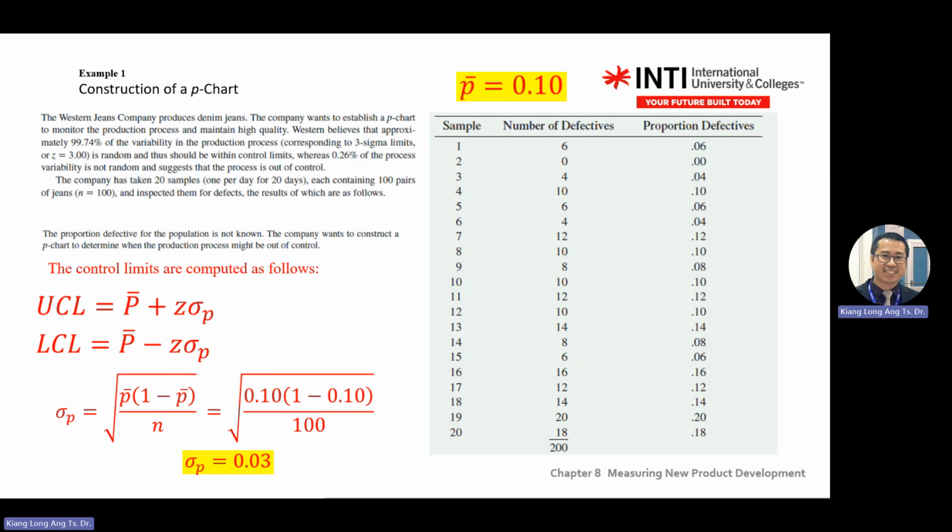So all this, you build the chart, you calculate the proportional defect depending on the point. Then you calculate the UCL, and you tell me from the graph whether the trend is in control, how many in control, how many out of control, or overall the trend is going up, going down, or going up to where? And you must tell me the direction. Going up to UCL, or have a tendency to go down, moving towards LCL, or you can tell the trend is in control and the data is well distributed in the mean region.